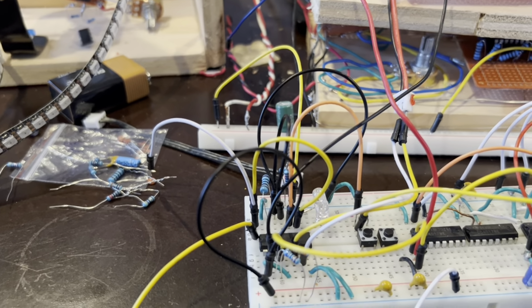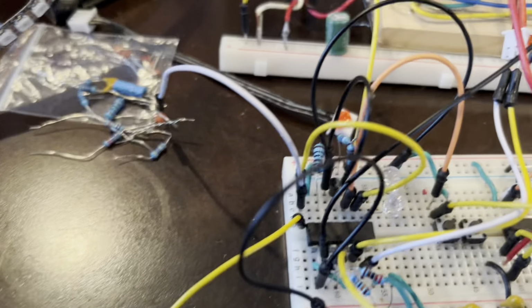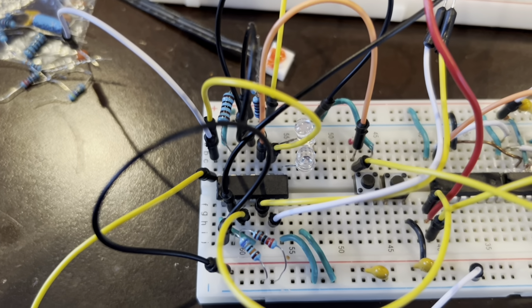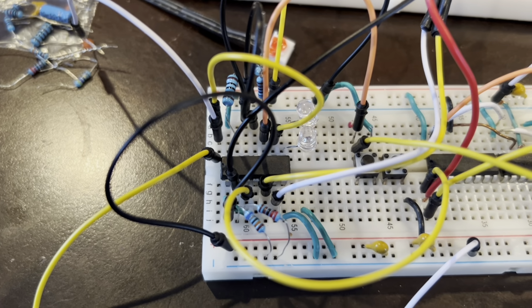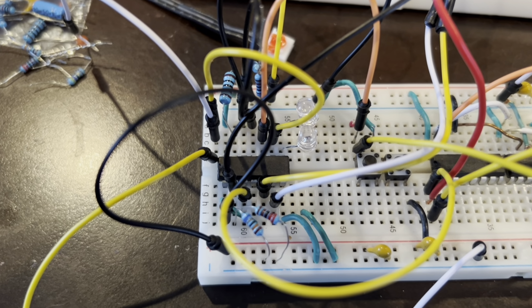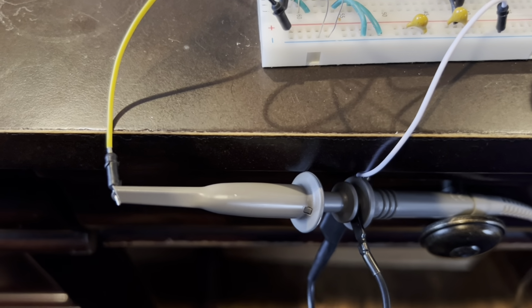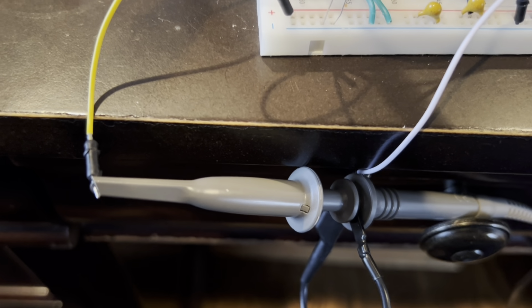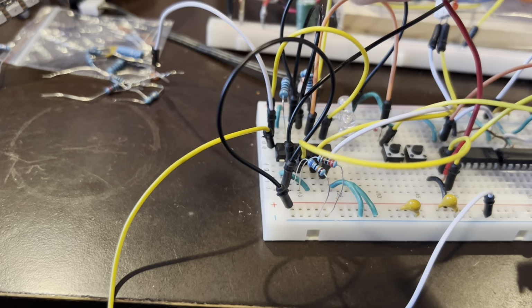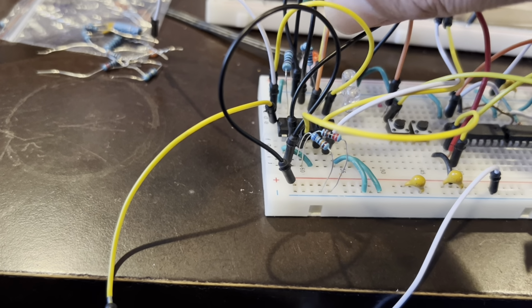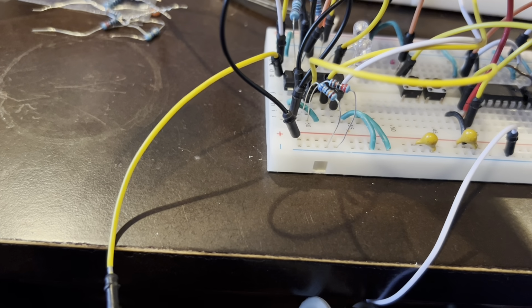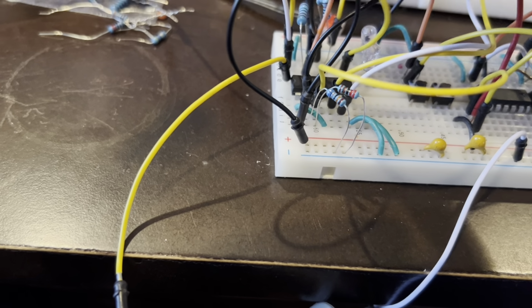And on top of that, to convert, this is done with a D flip-flop, a single 74HC74. And this is just the propagation delay in the circuit between the set and the reset. So all I have to do is switch this to there, and switch the clock signal to the reset.